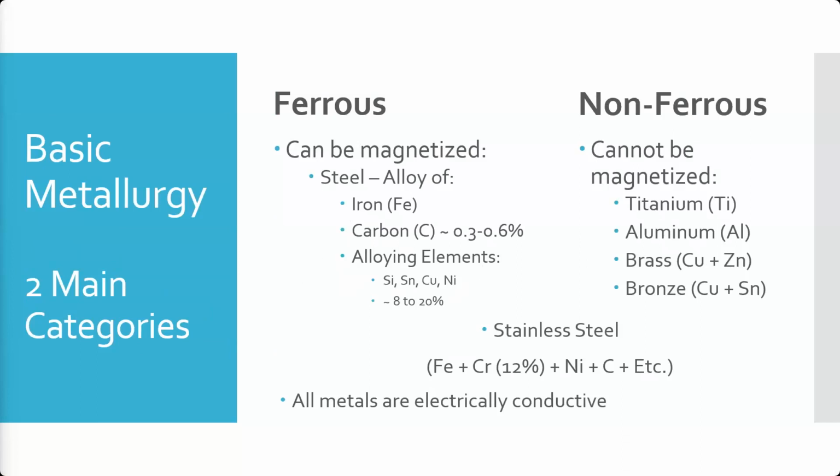We'll get into why when we get into ultrasonic testing, but essentially metal is pretty uniform, right? So if you pass a sound wave through it, ultrasonic is sound waves, it's going to move through it pretty smoothly. But if you think about a composite where you've got all those layers of fiberglass together and then layers of resin between them, that sound wave is going to pass from resin to fiberglass to resin to fiberglass to resin to fiberglass, right? It's going to change that sound wave every time it goes through one of those layers. So you have to keep that in mind when you're looking at what parts you're testing, what kind of tests you can do.